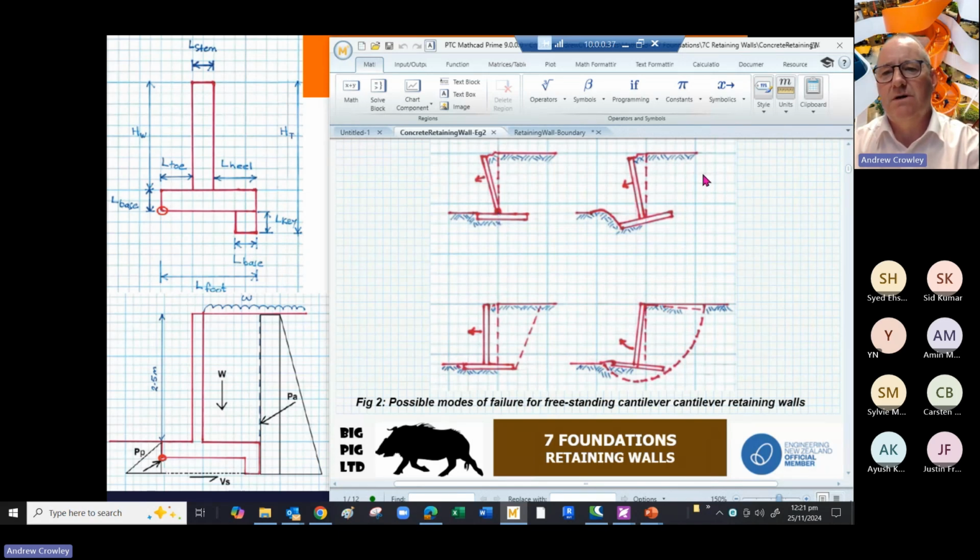The next two are about geotechnics. So the ground underneath can't take any more load and basically moves and yields under the pressure. Alternatively, the wall can slide out of the way. So you're pushing on the back of a wall, it just might move out of the way. And finally, your deep-seated rotational failure. You have a guess at which of the circles will cause the failure. So you're looking at the lower limit for that.